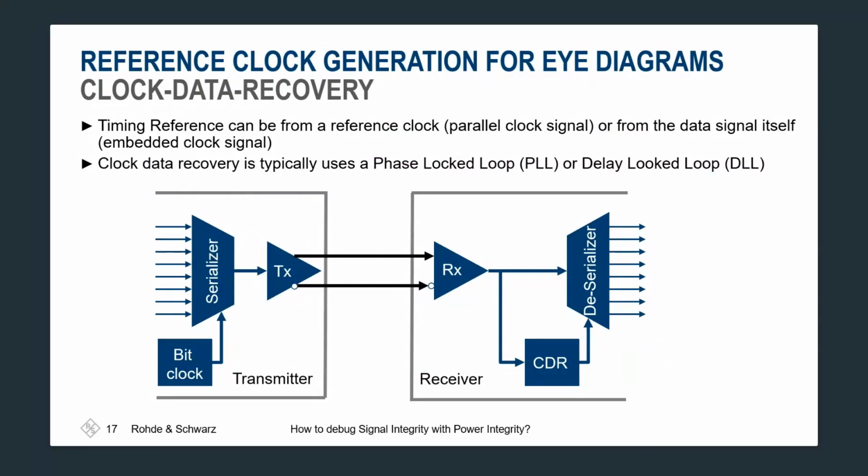The loop filter prevents fast changes in the phase error from being fed back to the VCO, and as a result, the VCO is adjusted only on slower changes in the phase error itself. In this way, the PLL acts like a flywheel in that the average frequency of the VCO is steady even when there are rapid changes in the phase of the reference signal itself.